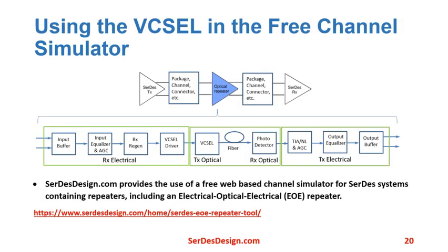This VCSEL model can be used in the free SerDesDesign.com channel simulator, which is a web-based channel simulator for repeaters, including EOE type repeaters. During this webinar, the discussion was focused on modeling of the laser VCSEL and its driver as used in an EOE SerDes system.